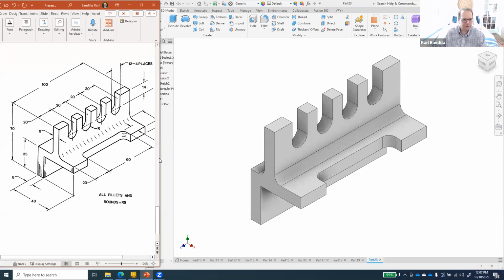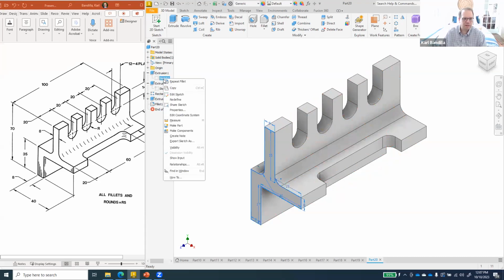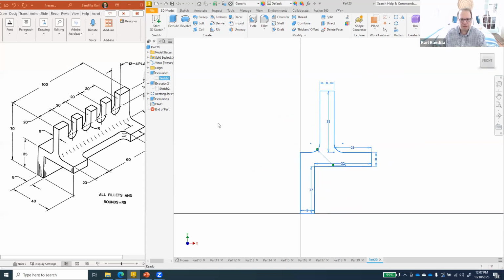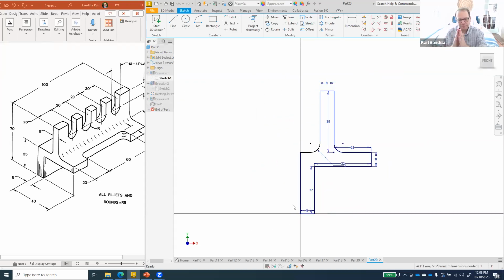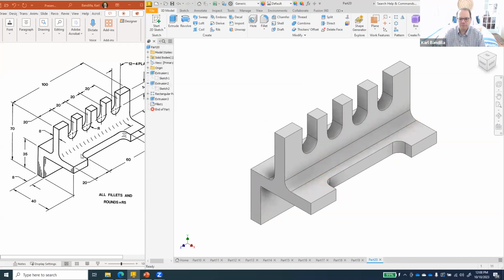And if we go back, let's see if Inventor can go all the way back to our very first drawing. So let's open this up, right click on the sketch and do edit sketch. Now we have to pray that if we change one of these dimensions here, it's not just gonna blow everything up, but let's see. So if we go back into the 32 here and say that this actually is not 32, but it's actually 40, did not change anything else, that was good. And we go back, then this looks a lot more like what this drawing looks like, right? So I think they just got that wrong.